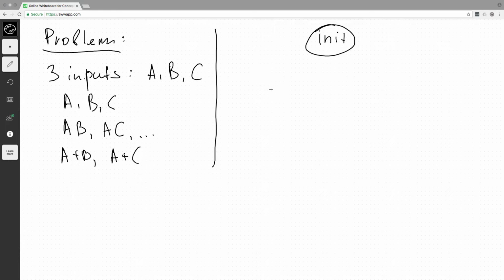As long as the finite state machine is in that state, any corresponding input, either A or B or C, will trigger a particular output. So this would be the case of the Mealy finite state machine, where one same state can serve output updates just with respect to the input change.